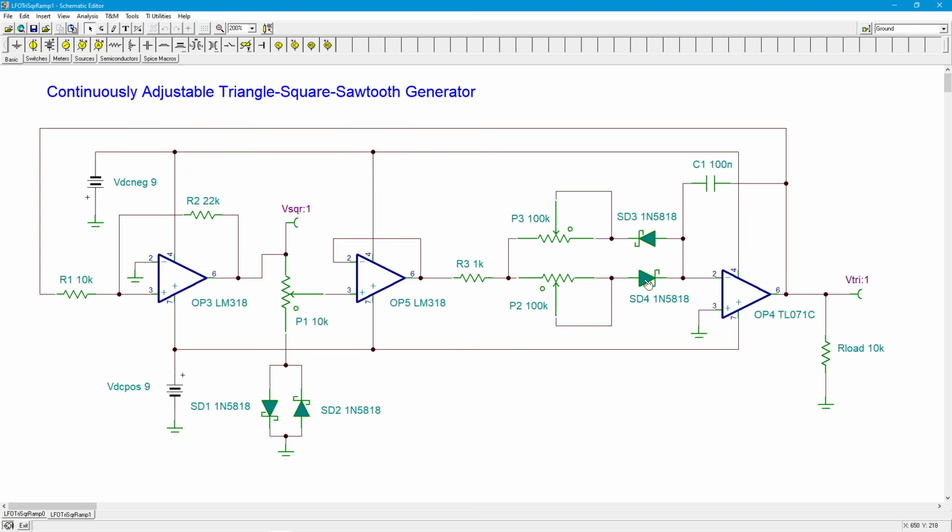Subtract off the Schottky potential. So, we had, I think, 7.4, something like that, volts out of here. So you should drop that off. So now it's going to be like 7 volts. But that 7 volts drops across this resistor and this rheostat. So depending on where the rheostat is set, that will set the current. And that current is what's going to go through C1 to create, again, that charge rate. And that voltage, again, gets sent back here into the little comparator with hysteresis. And we're back to where we were in the explanation a moment ago.